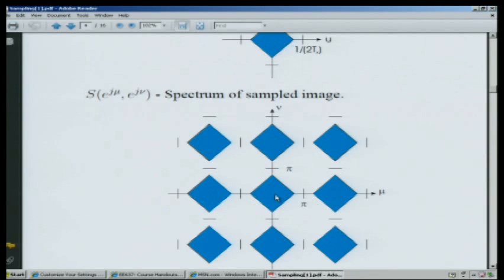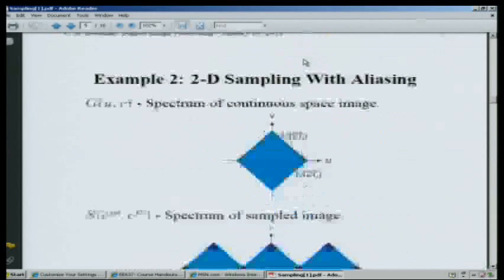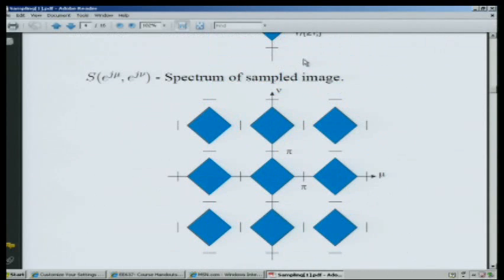So all the information in the frequency, I mean, if you have this function, you can certainly calculate that function, right? So this function contains all the same information as that function. Now, that wouldn't be true if there's overlap. Because there's no overlap, they contain the same information. So if the frequency transforms contained exactly the same information, then the signals in the time domain or space domain must also, because there's a one-to-one relationship with them, because it's an invertible transform. So basically, if you don't have aliasing, you can get perfect reconstruction.